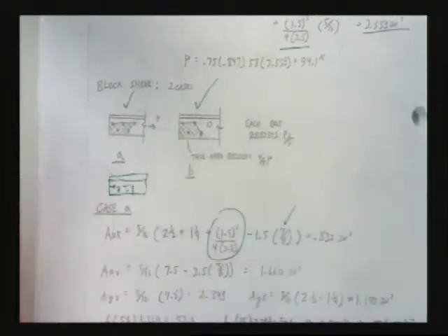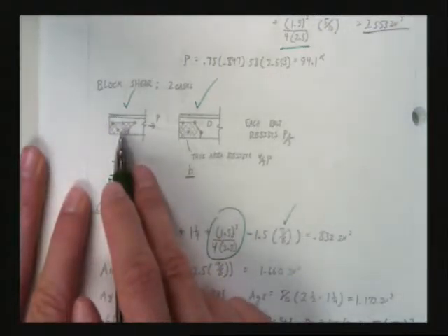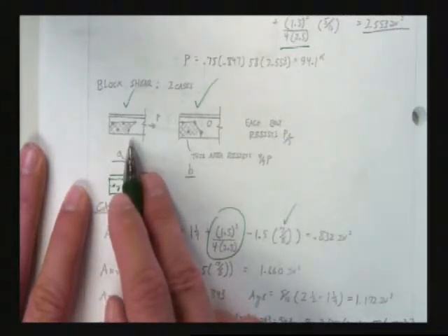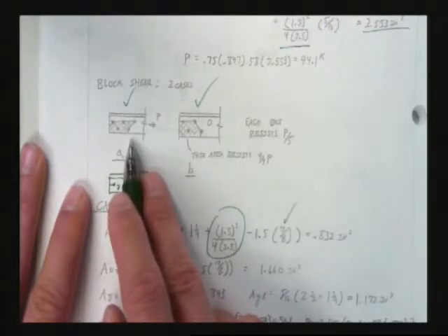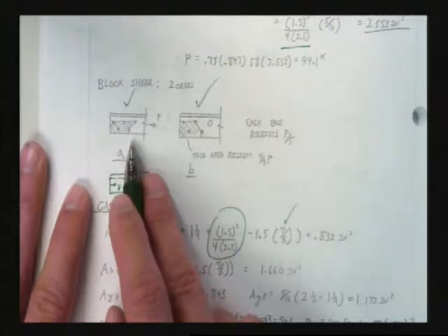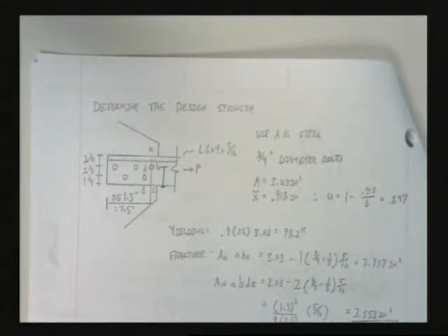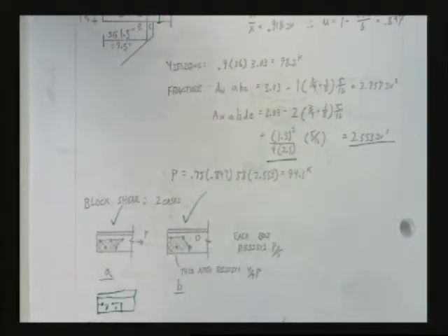You have to say, okay, when I'm calculating block shear, I know that I need AGVs and ANVs, and those are no problem. I can get those as I always have. It's the ANTs that are giving me the issue, right? The net areas in tension that I don't really know how to do. What is a conservative or rational way to handle that? Have I worked any problems similar to that? And hopefully a bell goes off in your head that says, yes, you have. That's when we were just doing the pure s squared over 4g calculation, right? So I'm going to use what I know from that to help me out with this problem. There are going to be examples like this in this class over and over again that aren't apparent. But through using logic, you can come up with a good way to attack the problem.